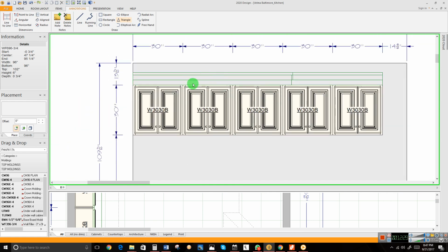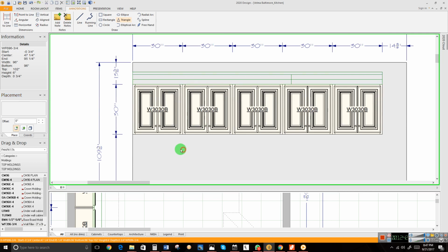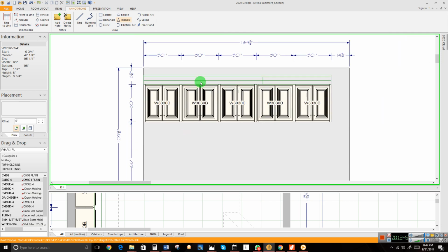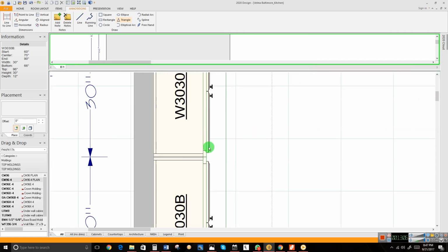Then if you want to stack molding, then you can always do your math. Put the vertical one first. Even if I want to do something, take a look at this before I conclude. Let me just delete this one. Now learn something though. If you want to adjust the entire molding, the stacked molding, the one you started with first is the one you need to modify. Now I'll tell you why, because that is the parent molding. The rest are all attached to it.